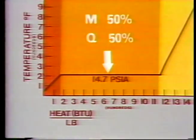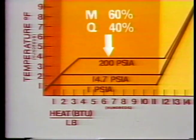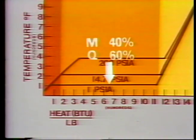For example, at this point in the transition zone at 14.7 PSIA, we have a moisture content of about 50% and a quality of about 50%. If we raise the pressure to 200 PSIA, the percentages change. Now the moisture content is about 60% and the quality is around 40%. By the same token, if we lower pressure to 1 PSIA, the moisture content decreases to about 40% and the quality increases to nearly 60%.